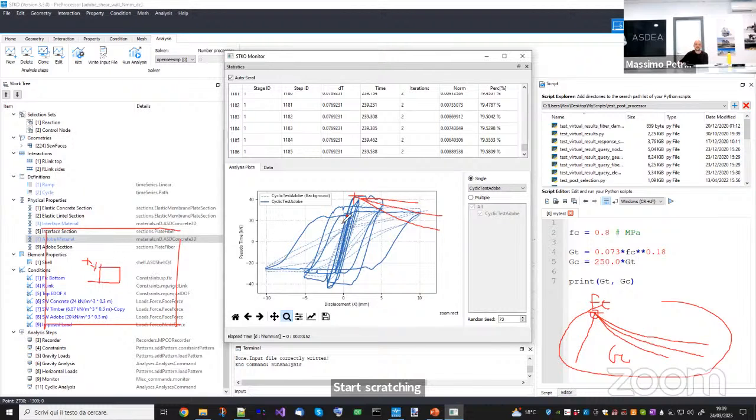Imagine the first cracks happen here; the first time the system goes down in softening is when the crack is completely open. But if you overestimate the tensile fracture energy, the crack will develop in a much slower fashion, and so it will allow the system to have an overestimated, apparent strain hardening. So that's why GT can influence the strain hardening first and then the softening.